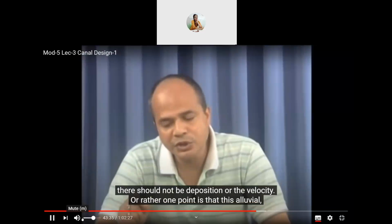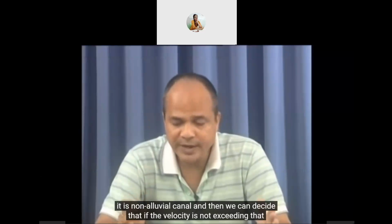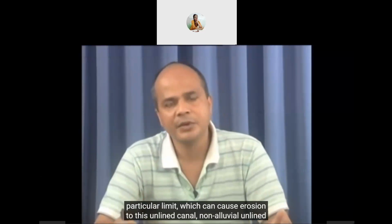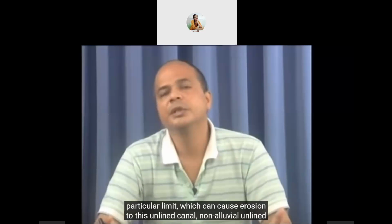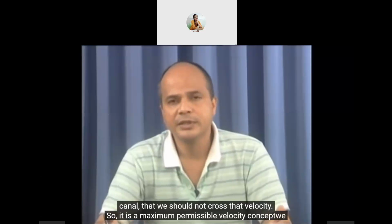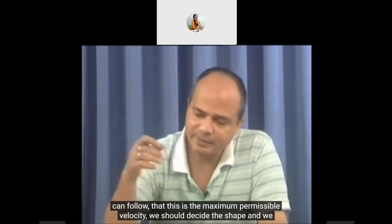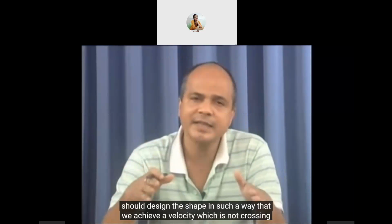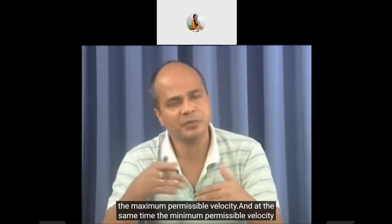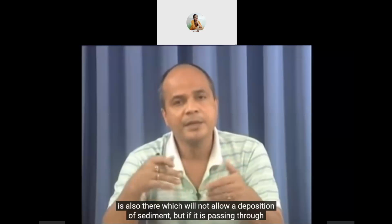For a non-alluvial unlined canal, we can decide that the velocity should not exceed that particular limit which can cause erosion. So it is a maximum permissible velocity concept we can follow. We should design the shape in such a way that we achieve a velocity which is not crossing the maximum permissible velocity. At the same time, the minimum permissible velocity is also there, which will not allow deposition of sediment.